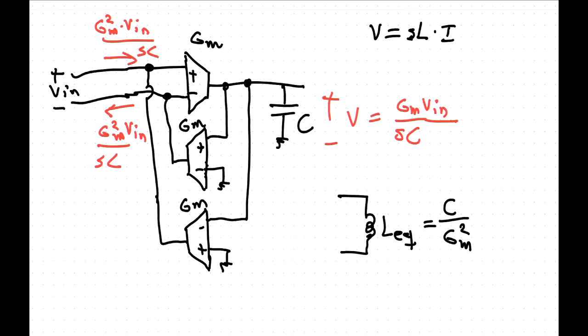When then do you need to use an inductor again? Yeah, it depends on what it is that you want to do. So you might not have to. So when do you need to use inductors? You need to use inductors if you're doing power circuits where you actually store energy in the inductor. That's an important part. So a switch mode power supply, for instance.